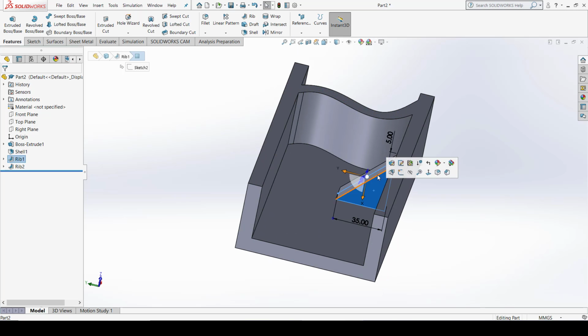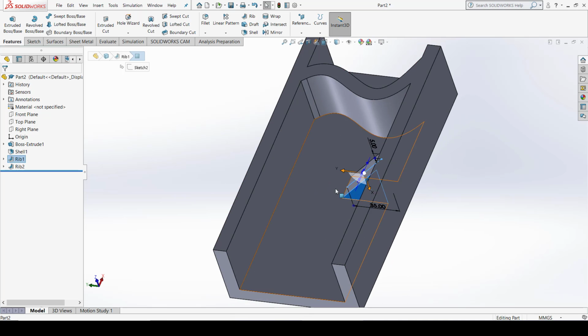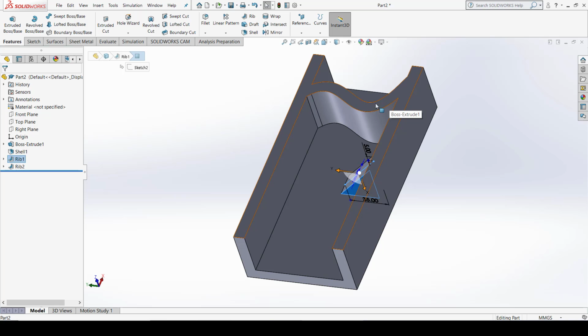And the first option is when the rib sketch is parallel to the rib structure. So these are the two options by which you can create the rib. Okay, so this second option of rib can be used when you create baffle structures, in boilers or any other condenser structures, or in tumblers also, where you have to distribute the material or you apply certain materials from other materials.